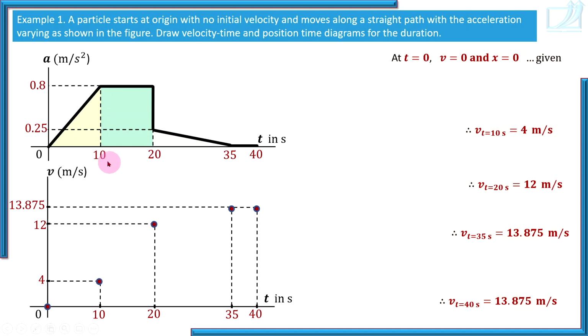you. So from t equal to 0 to t equal to 10 seconds, acceleration is increasing. What does that mean? Slope of VT diagram is increasing. Listen to me very carefully. Acceleration is slope of VT diagram. How do we use this information to draw VT diagram? Listen.